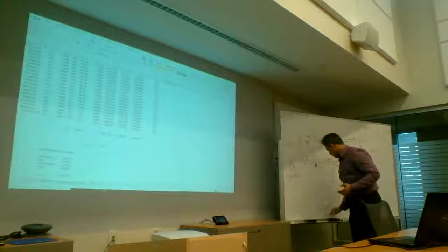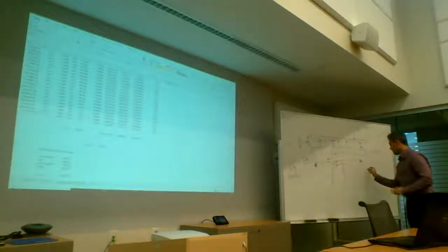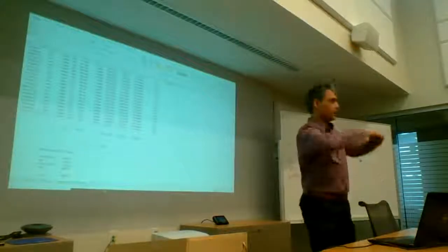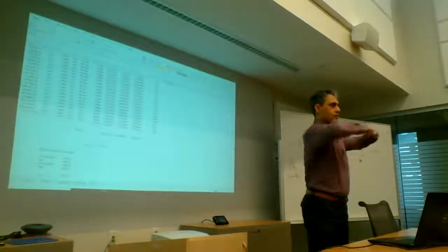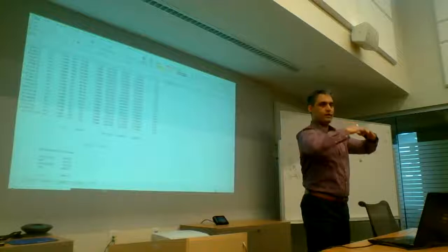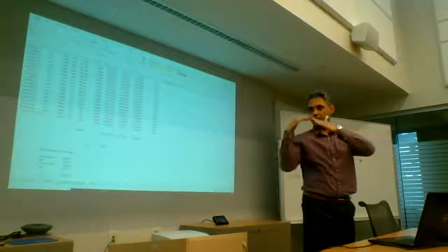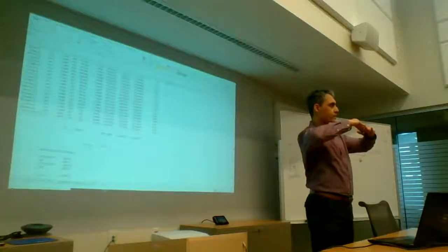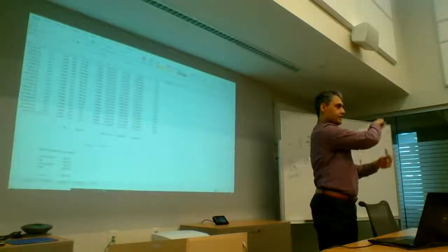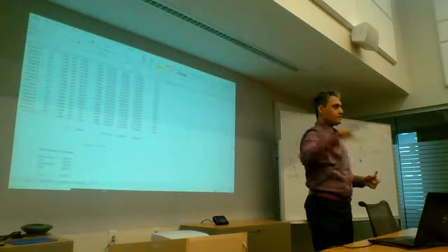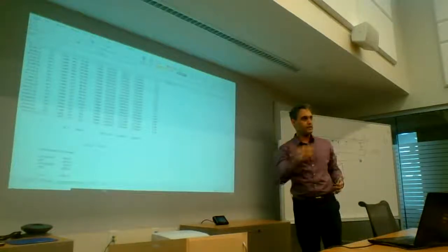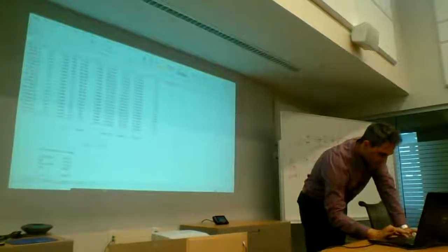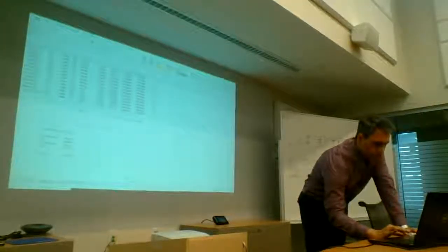So the mode shape, and I'll show you in a second. I think let's just show you on the graph, but your mode shape is like this. Okay, and that's when you get a very good comparison between CSI Bridge and this method. Whereas in reality, when you have a finite stiffness, your deck tends to curve up. And it gives you a longer period, and that's where they don't match very well. So here, you're not getting a very good match.